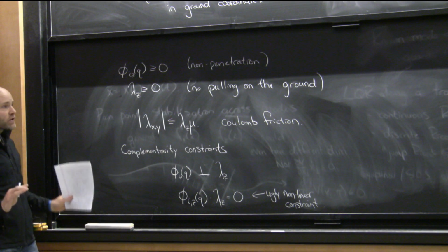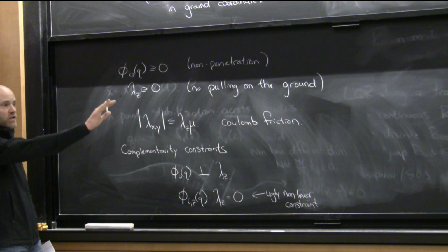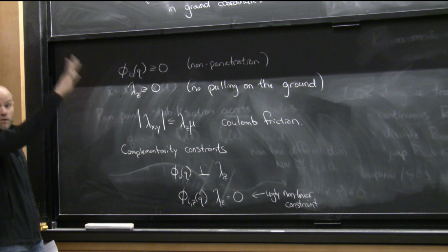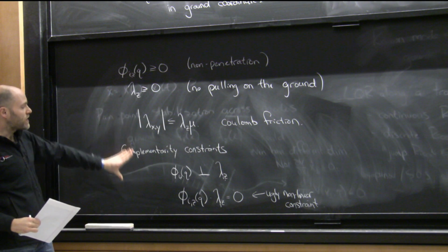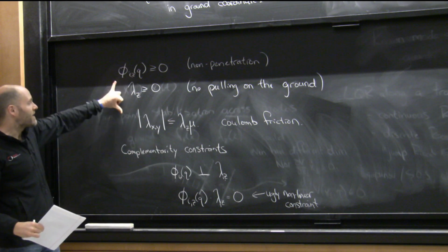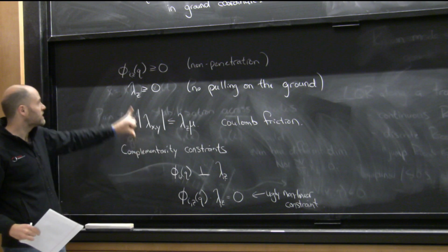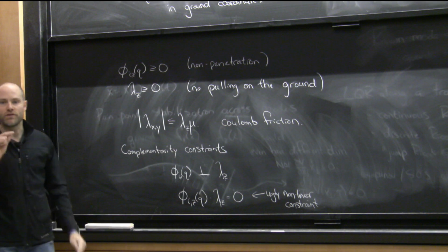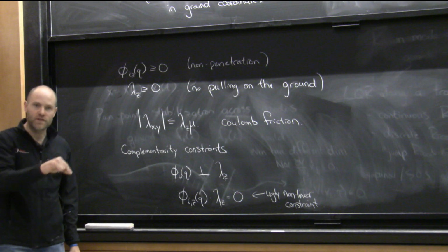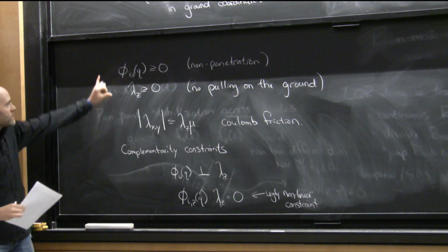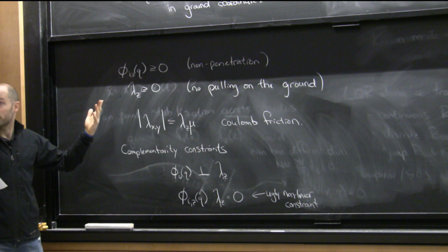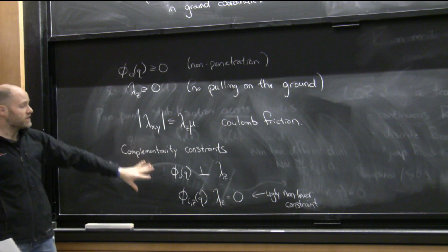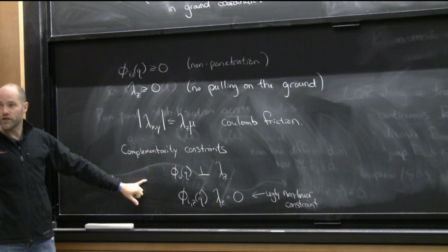Okay. So is that formulation clear? I can write down equations of motion using my favorite manipulator equations. Now the state space is bigger. It's the floating base coordinates as if there were no constraints. But I'm going to write down the set of constraints on that system in a relatively compact way. I could have made a big table, saying if this foot is in the ground, and this foot is in the ground, and this foot is in the ground. I didn't do that. I just wrote one set of constraints per contact point, which completely define my dynamics.